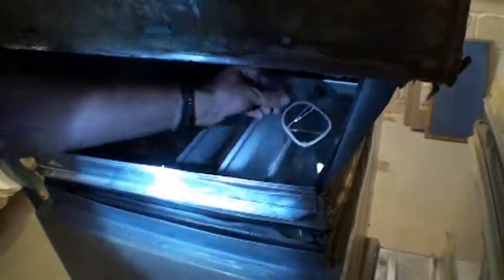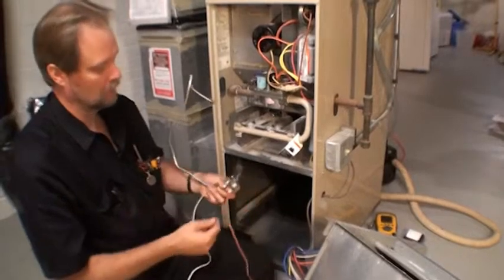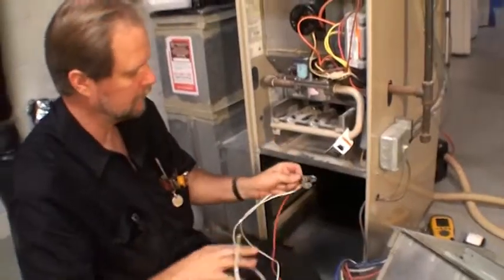If you cannot see the A coil from the furnace blower cabinet, you will need to lift the plenum and inspect the A coil and heat exchanger with a mirror. If you find a leaking A coil or condensate pan or a plugged A coil, you need to call Community Action. After passing the heat exchanger test, continue with the clean and tune by inspecting the igniter.